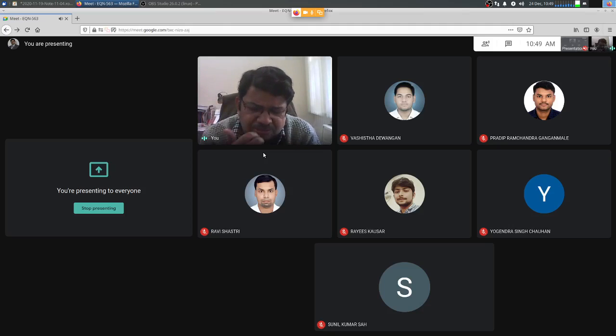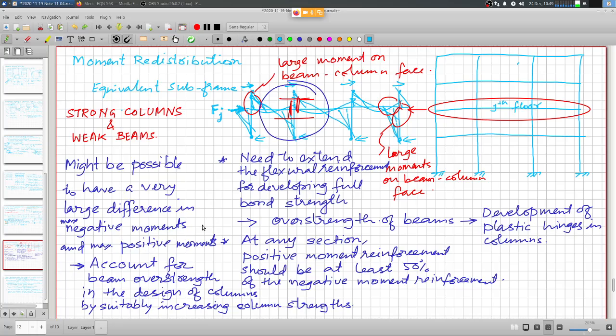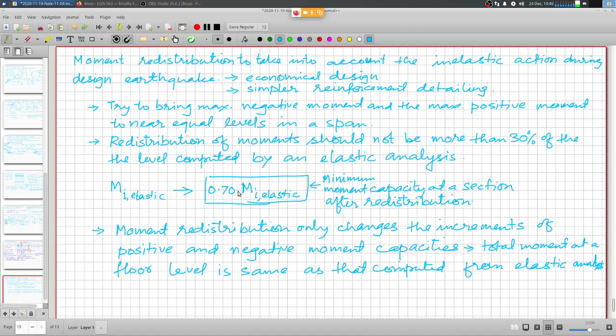And when you take into account all these and then go with the design, you will achieve obviously reduced moment capacities and reduced reinforcement requirement, because the moment capacities are reduced, and for positive moment you would anyway have reinforcement running in, so that will account for the capacities to take care of the positive moments as well.